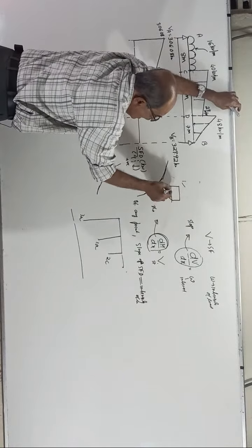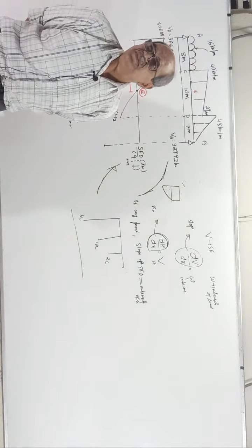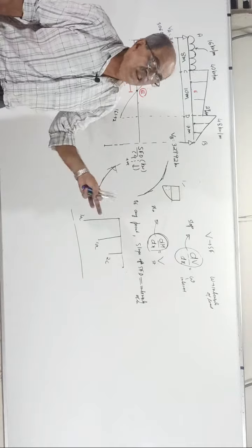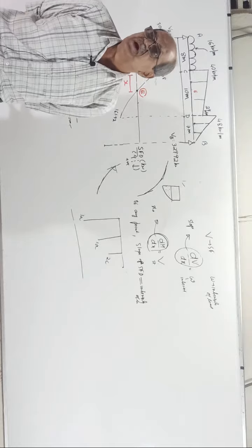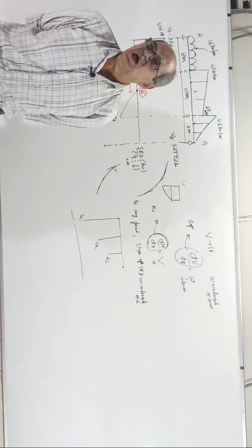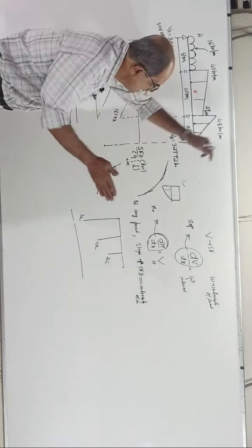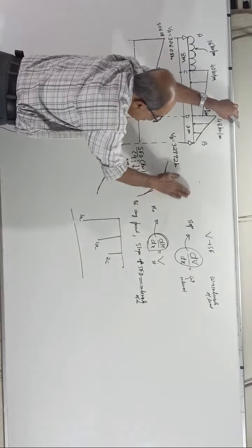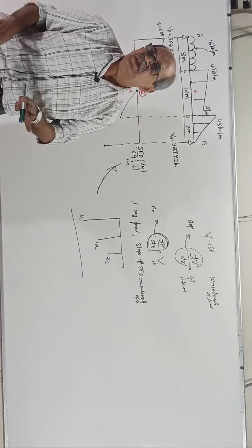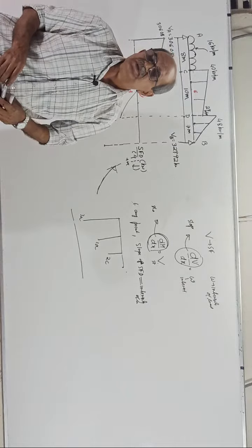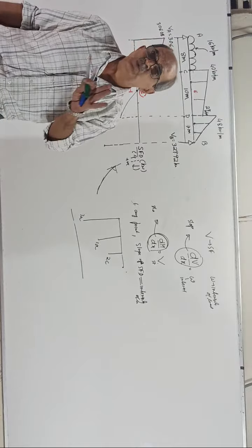For this parabola, people use area 2/3 base into height, CG 3/8 and 5/8. It is wrong. That is only for a parabola of equation y equal to 4h by L square into (Lx minus x square). Not for this parabola. But the error is too small. IS code only told, okay, use it. It may involve 1 or 2% error. Such RCC is still okay. But not in structural mechanics, strength of materials or structural analysis. You should give value to mathematics.